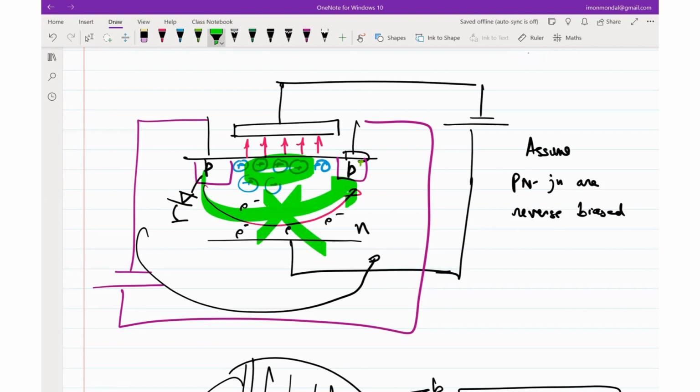So if a carrier has to flow, it has to flow through that space that is just underneath the capacitor. It cannot flow through anywhere else. Okay, fine. So far so good. But the real question remains, this guy is still devoid of any mobile charge, right? The place from which I want carrier transfer to happen doesn't yet have any mobile charge. So still we will not be able to get any current.